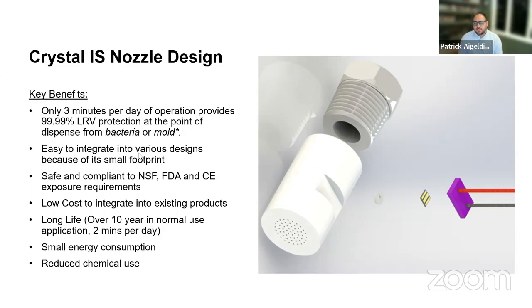And then the other safety component is the exposure risk to UVC. So part of certain standards within RoHS and CE require you to ensure that the material set can be exposed to UVC and also that the dose exposure is less than 3 millijoules per centimeter squared over the period of a day. So you're protecting the user from UVC exposure, and then you're protecting the user from shock.